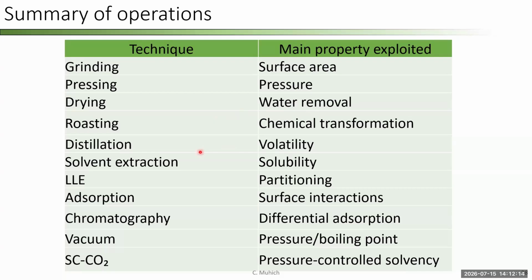Distillation utilizes differences in volatility. Solvent extraction utilizes differences in solubility. Liquid-liquid extraction uses differences in partitioning between aqueous and organic phases. Adsorption utilizes differences in surface interactions. Chromatography is differential adsorption, so adsorption including a time-based effect.